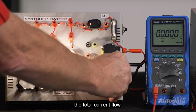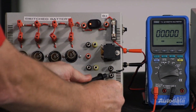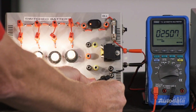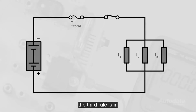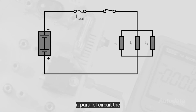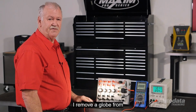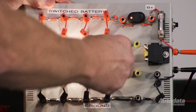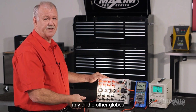The total current flow is now 2.5 amps. The third rule is, in a parallel circuit, the total current flowing in the circuit is the sum of the individual branches. If I remove a globe from a parallel circuit, it only affects that part of the circuit. It doesn't affect any of the other globes.